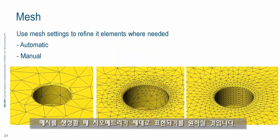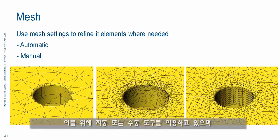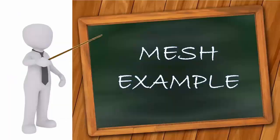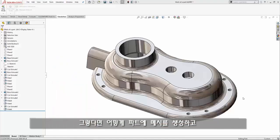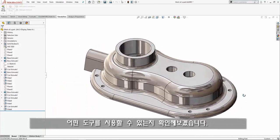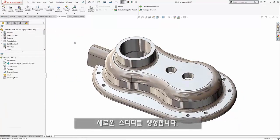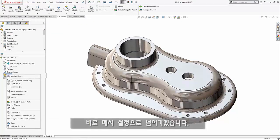Okay, so when we are creating a mesh, we want to capture the geometry in a good way, and for this we can use some automatic tools and some manual tools. We'll see how we can apply those in a moment. So let's have a look at how we can mesh a part and what tools we are using here. We are creating a study, and we are jumping directly to the mesh settings.